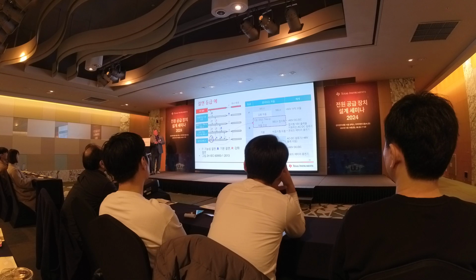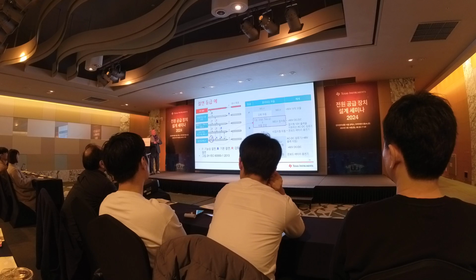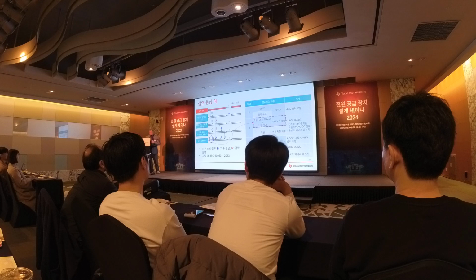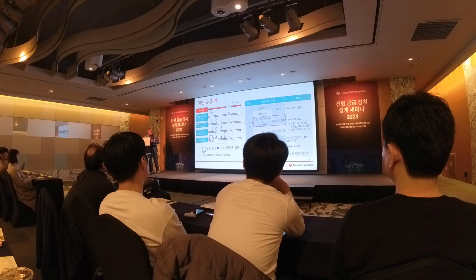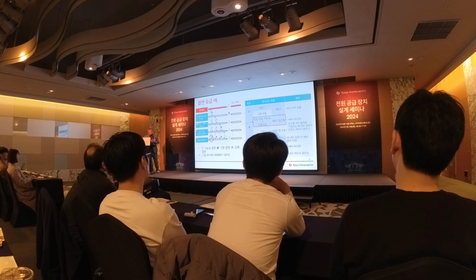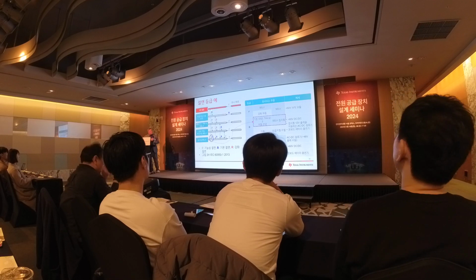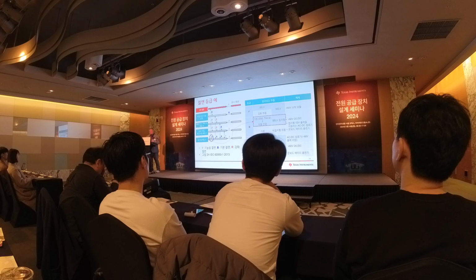So, if we look here to basic insulation, an example that's given here is we have an earthed safety extra low voltage, which is here, earthed safety extra low voltage, or one of these TNV2 or energy source class 2. For those to go between here and there, we need to have basic insulation.